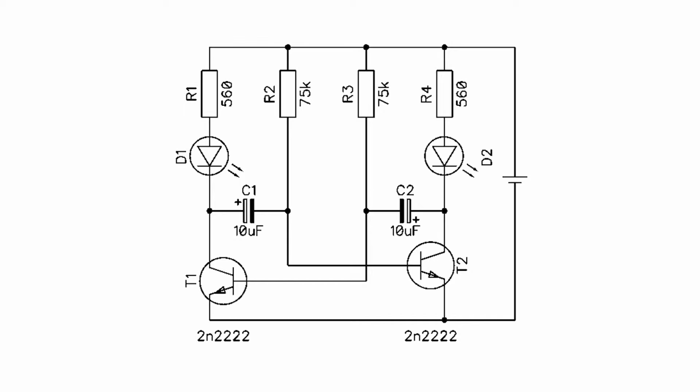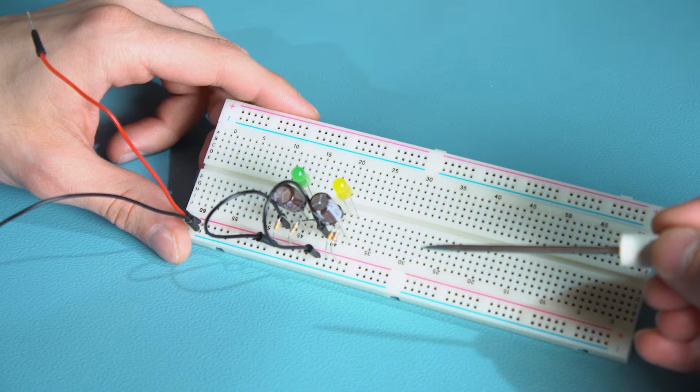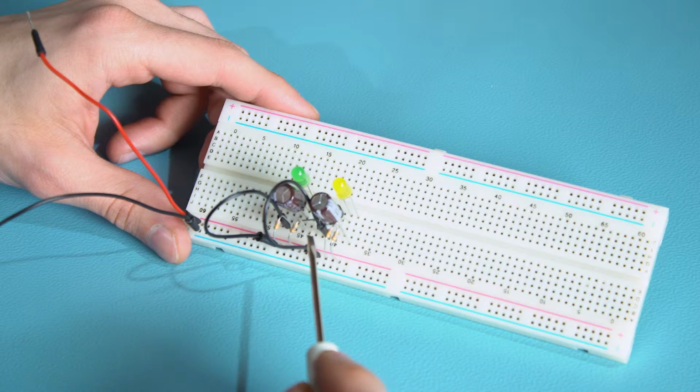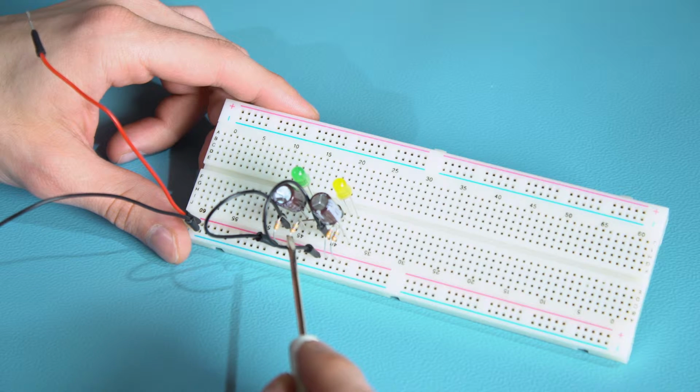To switch some load, for instance in the form of LEDs or motors, we need transistors. In order to be able to decide on the speed of these changes, we need elements that can somehow change the value of voltage or current in a given time. Capacitors are such elements. If we charge them with a small current, they will charge more slowly than if you would load them with a high current. In addition, the larger the capacity, the more time the charging will consume. We will need resistors for limiting the current and cooperation with capacitors.